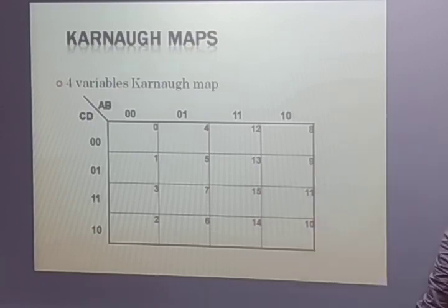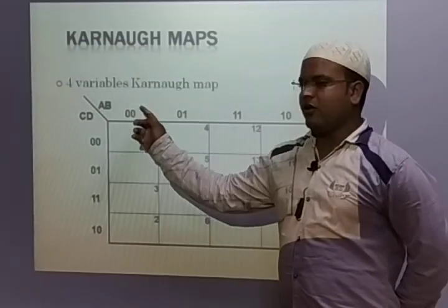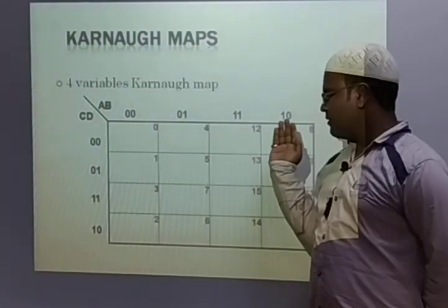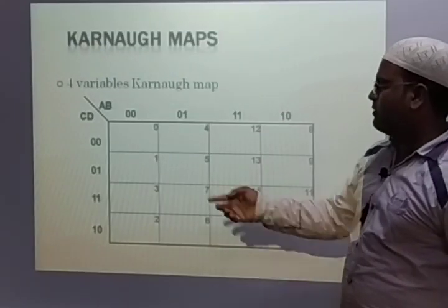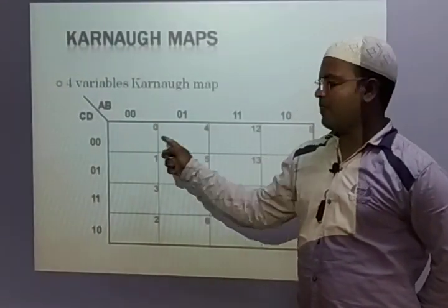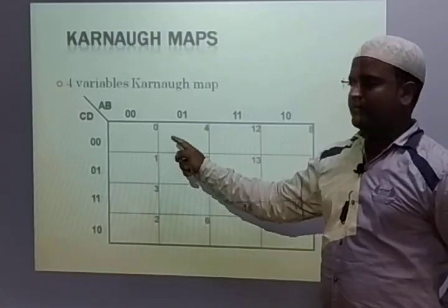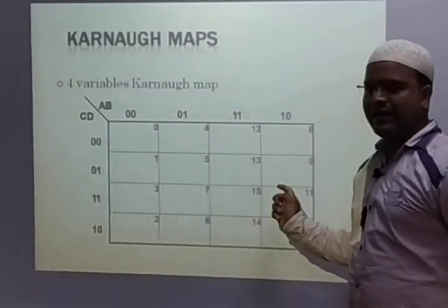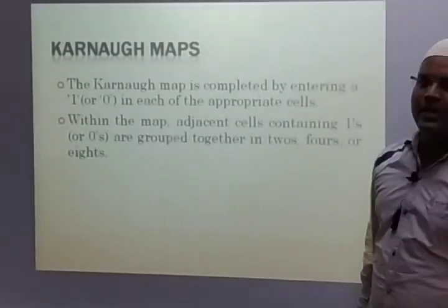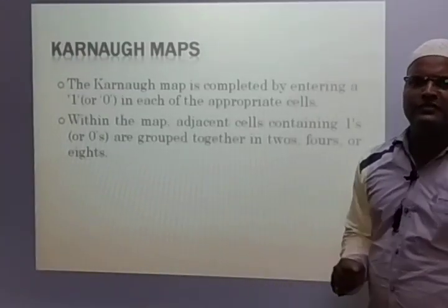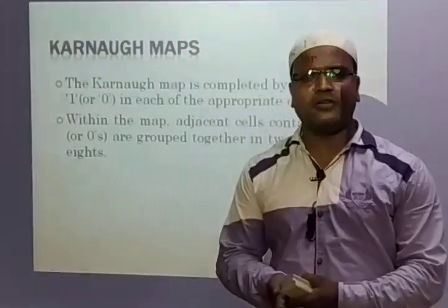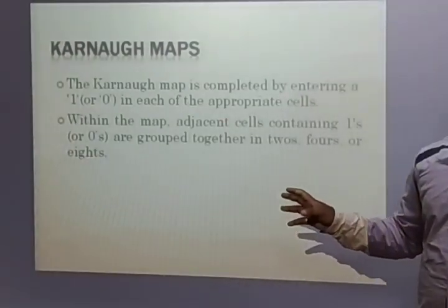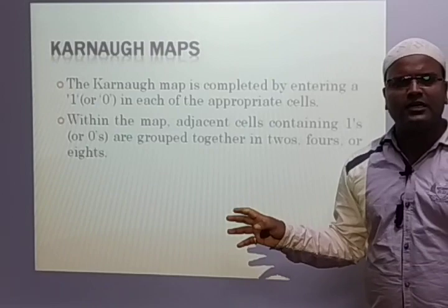Now this is a four variable map. In four variables, what do we mention? All four zeros, so M0, M1, then we go for folding, M2 and M3. See, 0, 0, 0, 0 is 0. 0, 0, 0, 1 is min term M1. So 0, 1, 2, 3, 4, 5, 6, 7, 8, 9, 10, 11. This is how your four variable K-map has been designed. We have seen this with the help of the blackboard method, and I have explained how we design and construct the K-maps. Here we just wanted to see the detail.